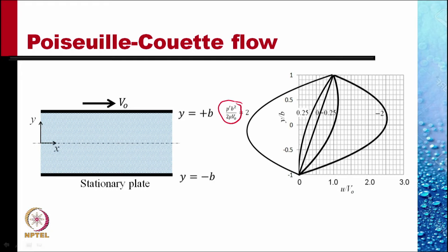Non-dimensional numbers. When there was no pressure gradient along the tube, then the profile was a straight line. For negative pressure gradients, the velocity profiles are like this and this. For a positive pressure gradient, that is, the pressure increasing downstream, the velocity profiles are pushed back, this and this.